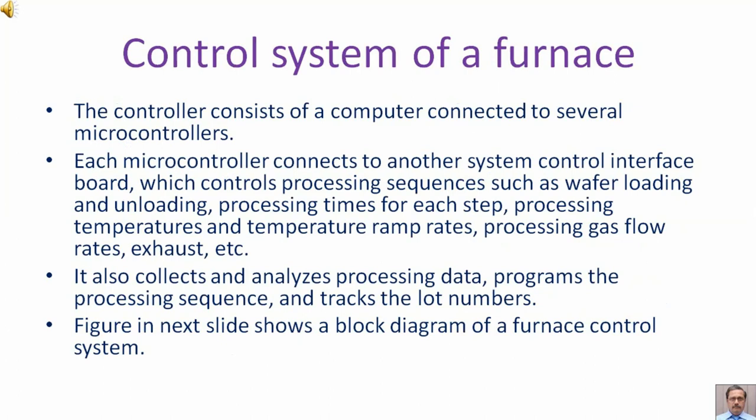Each microcontroller connects to another system control interface board, which controls processing sequences such as wafer loading and unloading, processing times for each step, processing temperatures, and temperature ramp rates, processing gas flow rates, exhaust, etc. It also collects and analyzes processing data, programs the processing sequence, and tracks the lot numbers.